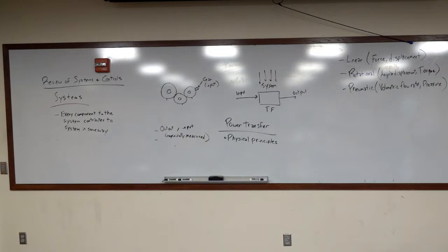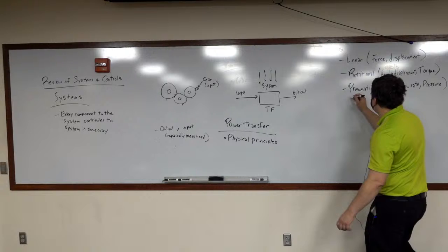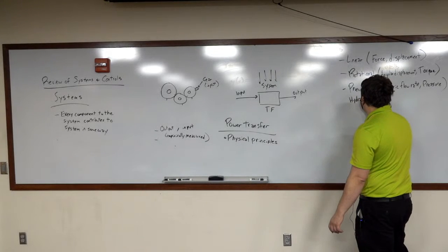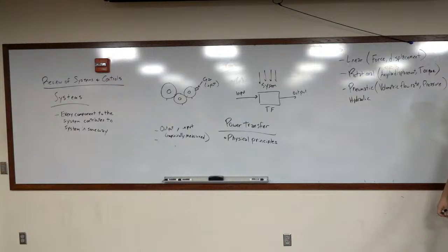This is a pneumatic system that also has the same principles as a hydraulic system. Again, they fall to volumetric flow rate and pressure. In a pneumatic system, you tend to deal with a higher volumetric flow rate because the compressible gases play more of a role, whereas in a hydraulic system, you assume the hydraulic fluid is incompressible. Therefore, you're dealing more with higher pressure systems, usually without nearly as much volumetric flow rate.